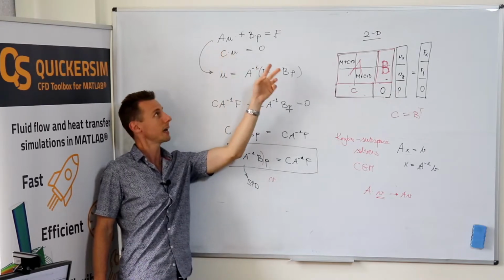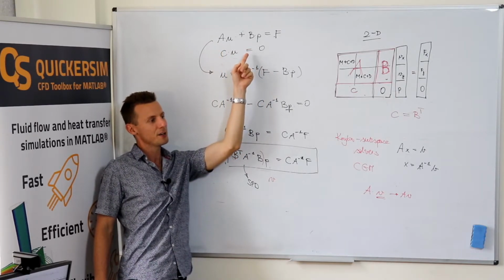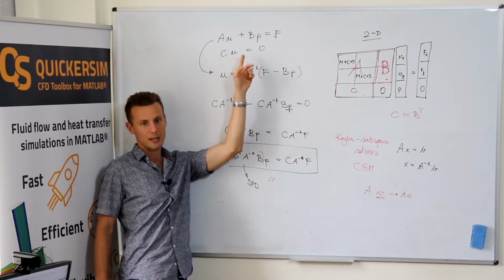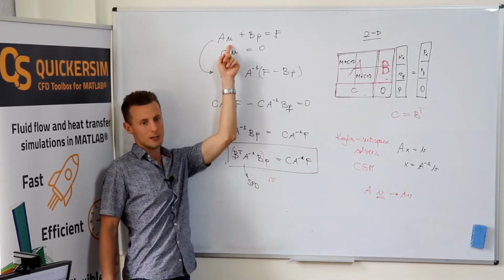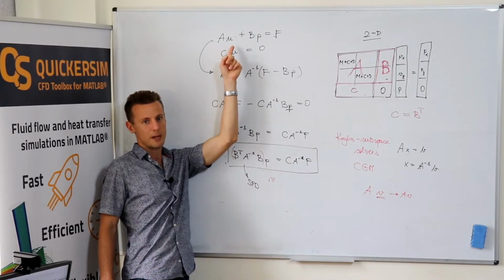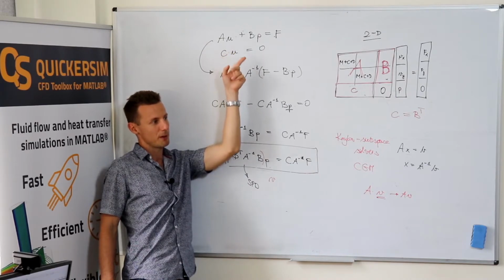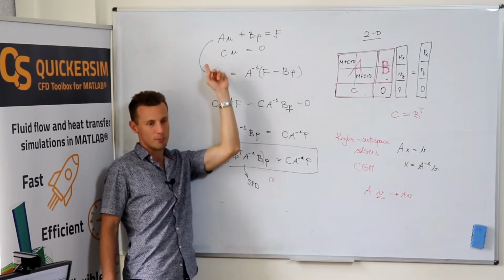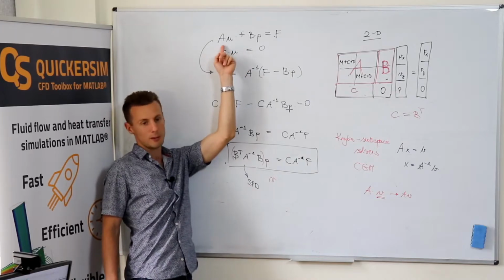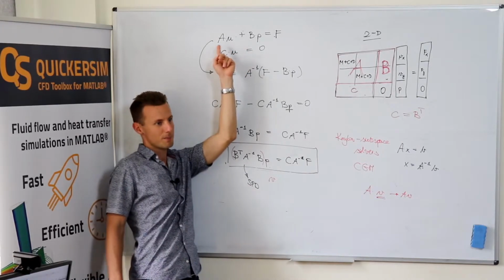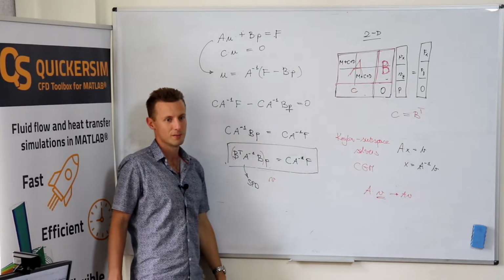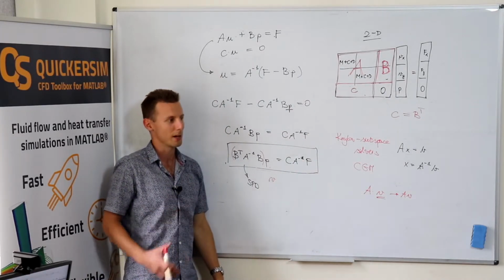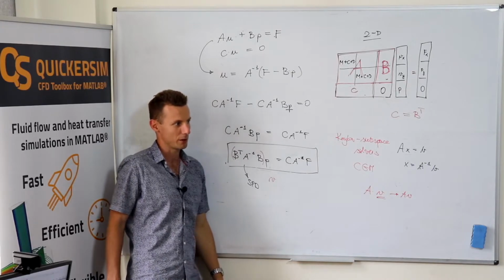So we've right now solved the linearized Navier-Stokes equation for the current velocity and pressure, but it was linearized, so we need to update the velocities, take the new velocities to the convective term, construct the A matrix again, and iterate the nonlinear terms. Good luck with that.